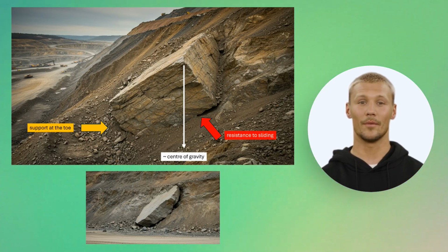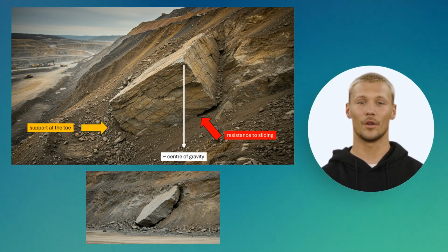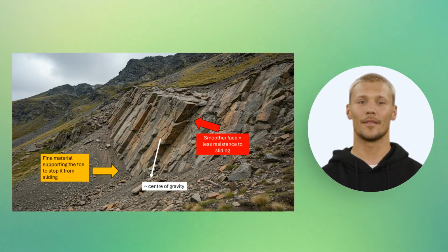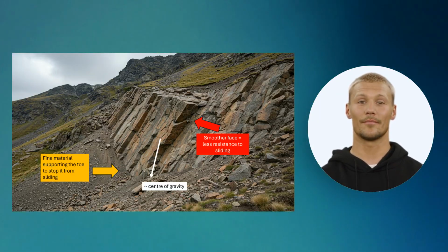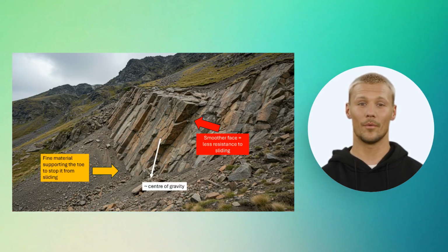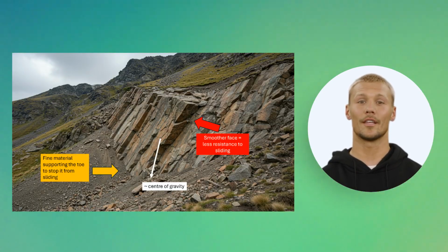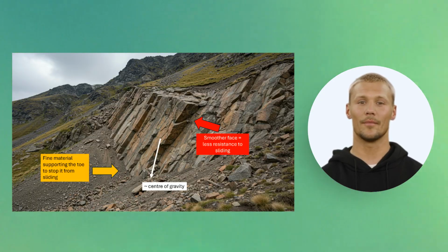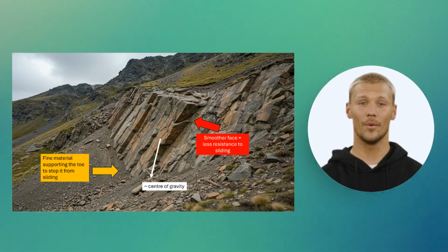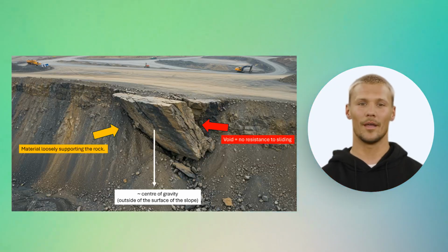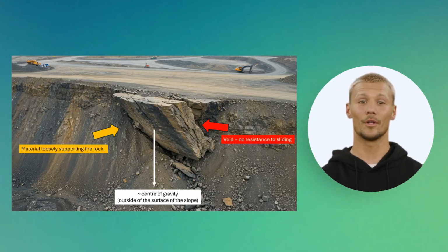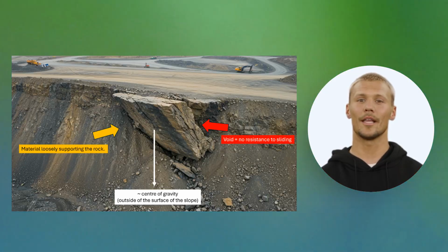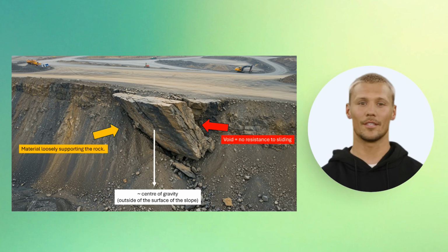This increases the clamping force and resistance along the breaks or joints in the rock, helping to hold it in place. However, as the center of gravity moves closer to the exposed face, there is less weight pressing down onto the support surfaces and less resistance against sliding or toppling. Then, especially if erosion, blasting, or excavation removes the supporting material around the anchoring point, the overall stability decreases. Now, if the center of gravity moves beyond the edge of the slope, with no material left to support it, the likelihood of instability or failure increases significantly.